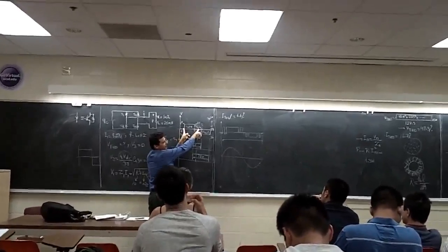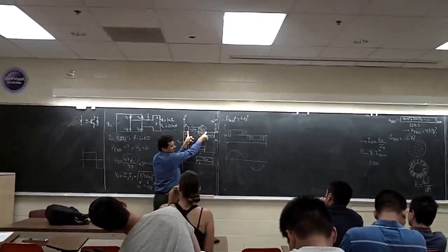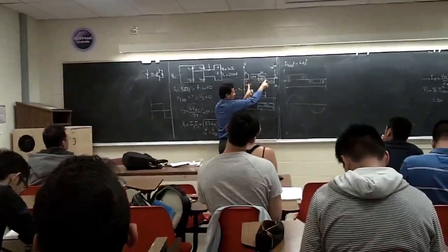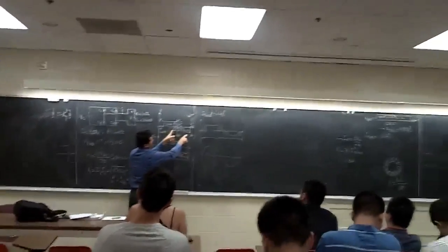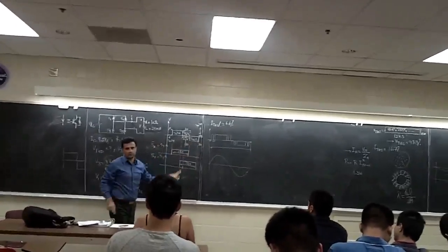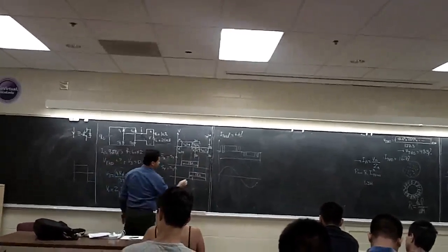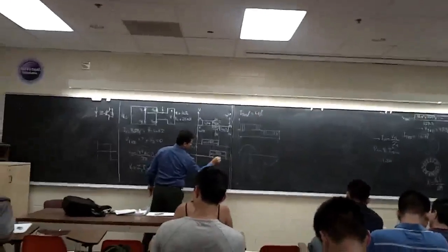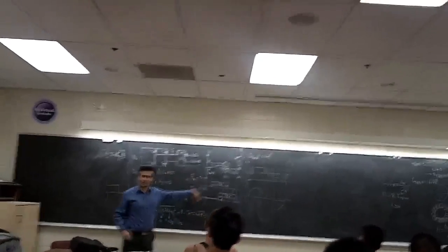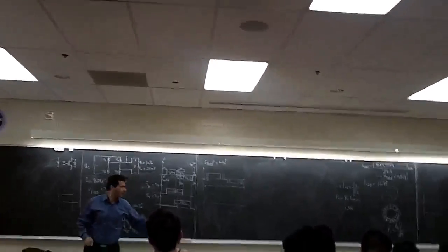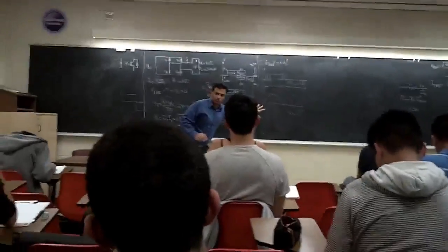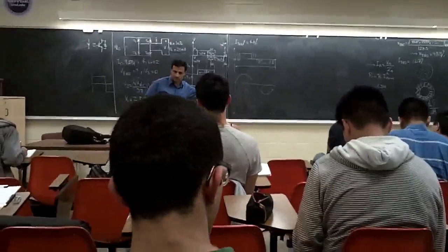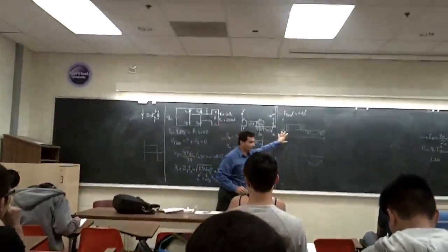If I go alpha degrees this way and alpha degrees this way, it still is 180 degrees, right? And you can see S1, 180 degrees. The same thing here for S3. You can go for S3 from here to here. This is the switching pattern for this one, 180 degrees, 180 degrees. If you send this to your gates, you're going to see that voltage at your output. They call this one switching pattern. This is very simple.